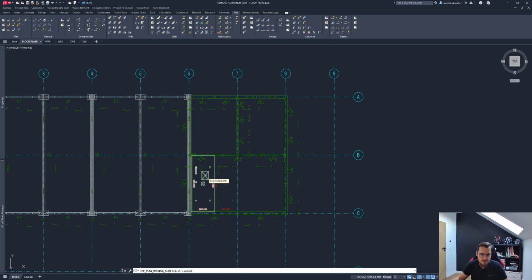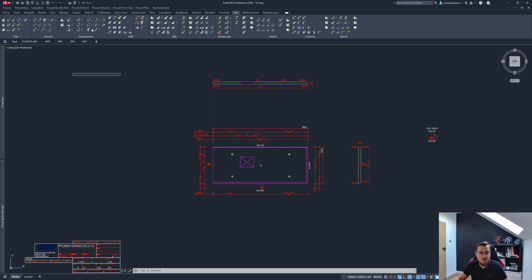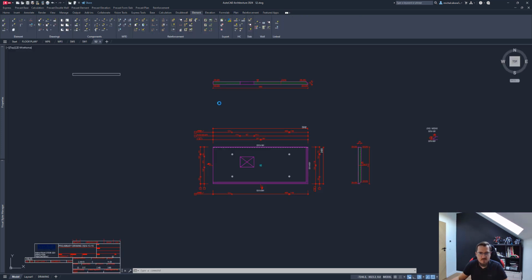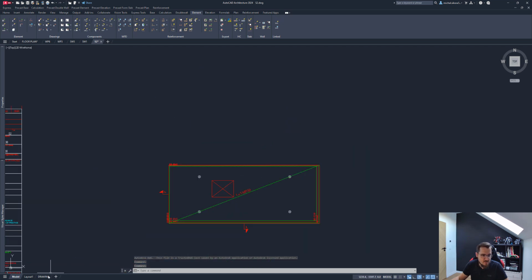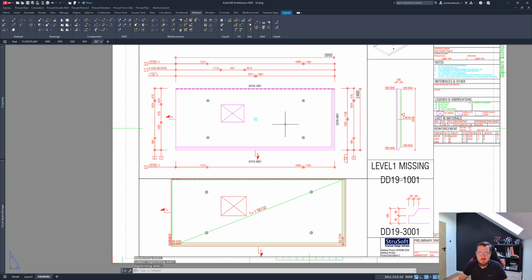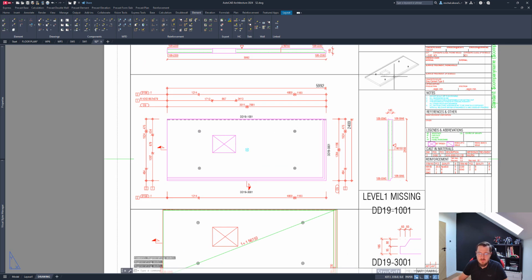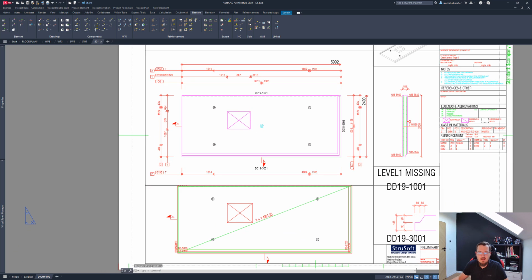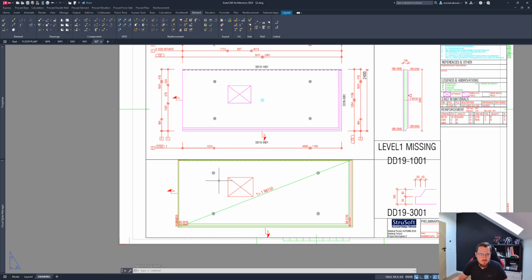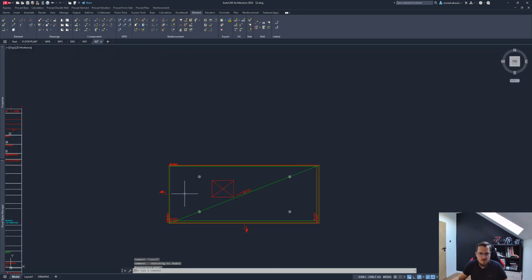Slab. There are so many icons, sometimes I have a hard time finding the proper one. All right, okay. So that's the very quick automatic drawing of a slab. We can also create a 3D preview of that. There's a section view as well for the slab, both the longitudinal and transverse. Of course, we could work with adding some reinforcement to openings, if need be. There are tools for that. So no problem there. Maybe we can try doing that.